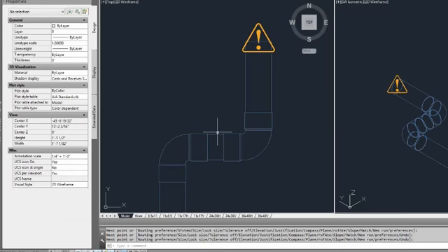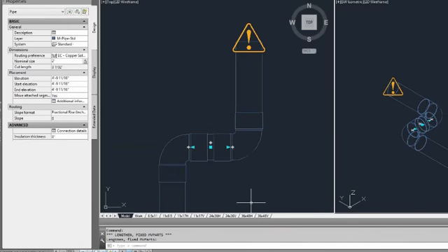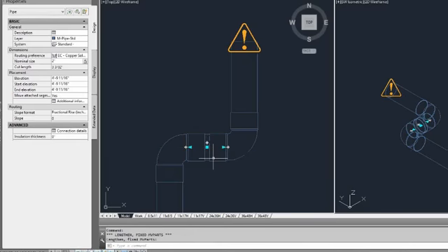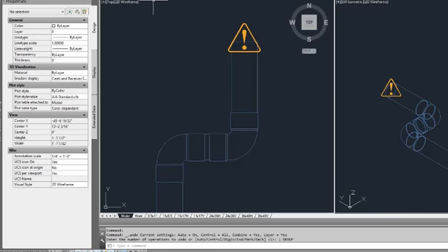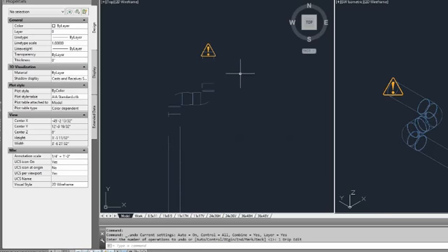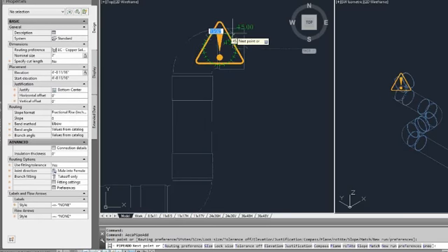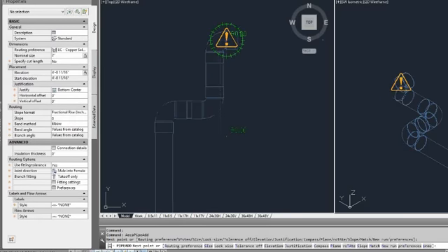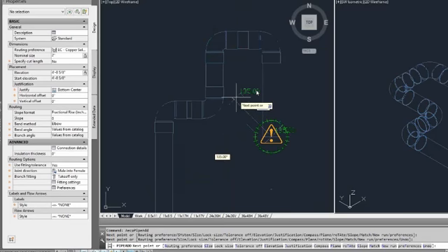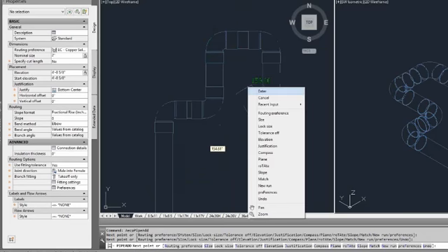Now in reality, you can probably make it a little bit smaller, but it'll go to the smallest that it can be, and then it'll start to push this other piece of pipe back. So in back-to-back fittings, definitely use your 90s and just put in little short pieces of pipe, and it'll do the best that it can to get you there.